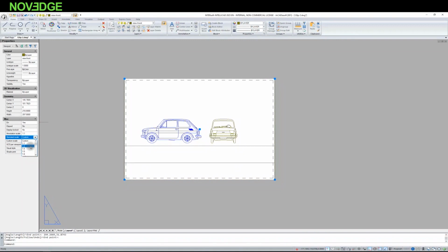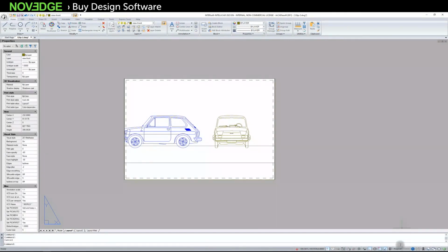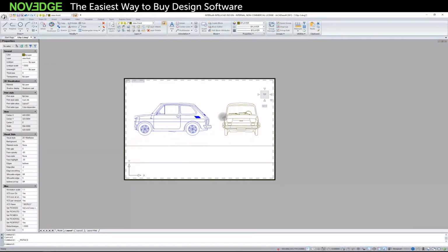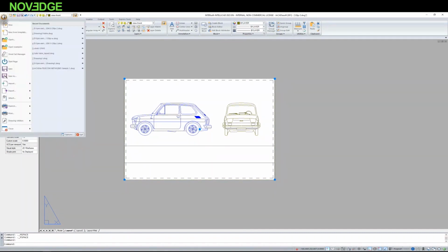This sheet is scaled 1:1, but my viewport is scaled 1 to 20. I'm going to choose 1 to 2 because of the offset of this unit of mine. I will center my model, which I want to print. I'm moving it. Of course, the viewport can shift. That's why right after I lock the viewport back, I check if it accidentally shifted. It's still 1 to 20, or 1 to 2 entered here due to the fact that it's centimeters. I scale it to millimeters, and I have a print in the scale of 1 to 20.